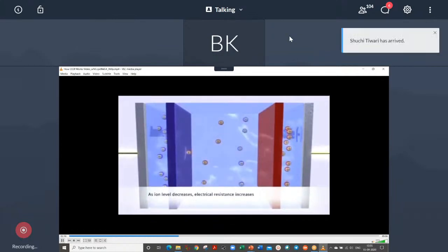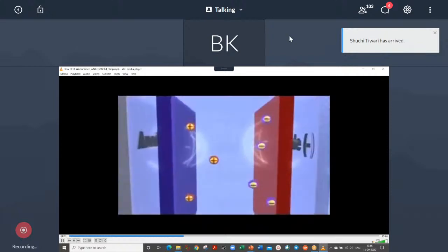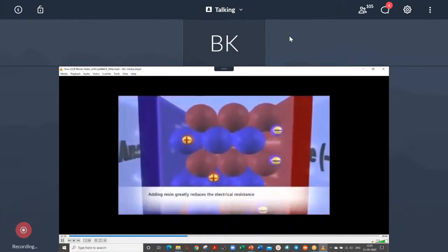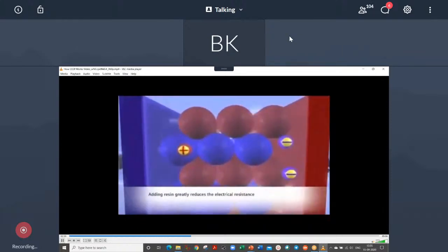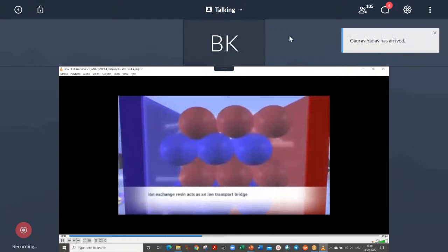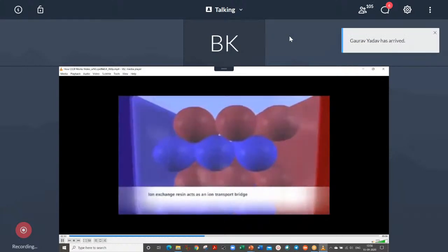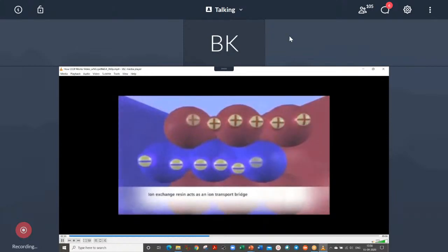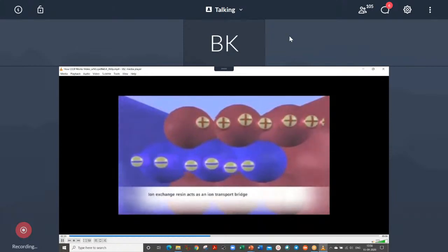Ion Pure CEDI technology solves this problem by sandwiching a mixture of cation and anion selective resins between the two membranes. The large surface area now offered by the resin beads effectively eliminates the ion diffusion resistance and allows the ions to move freely, even in ultra-pure water solution. The surface of the resin beads acts as a conductive path, effectively acting as a bridge for the ions to move quicker toward the membrane surface, faster than if they were in water alone.